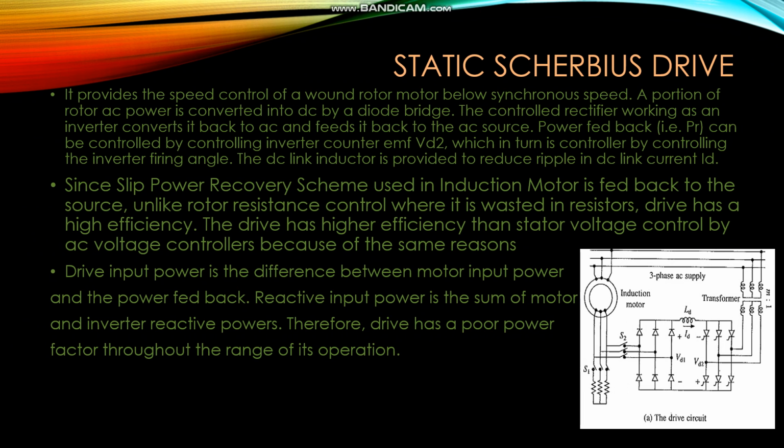Reactive power is still consumed from the source, and the power factor is poor in this drive. Since in the slip power recovery scheme the slip power of the induction motor is fed back to the source, unlike rotor resistance control where it is wasted in resistance, the drive has a higher efficiency than stator voltage control by AC voltage controllers, for the same reasons. Drive input power is the difference between the motor input power and the power fed back. Reactive power is the sum of the motor and inverter reactive powers. Therefore, the drive has a poor power factor throughout its region of operation.